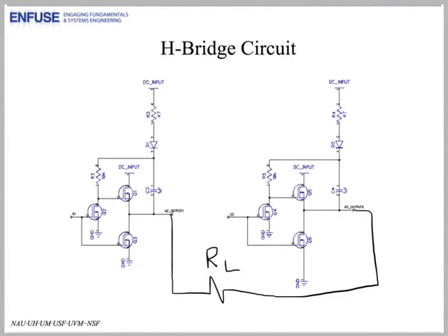Secondly, notice that the schematic shows 4 connections to DC input. Here, here, here, and here. On your breadboard, all of these can be connected to the same 5-volt DC power supply that powers the control subsystem. Now we move on to a question.